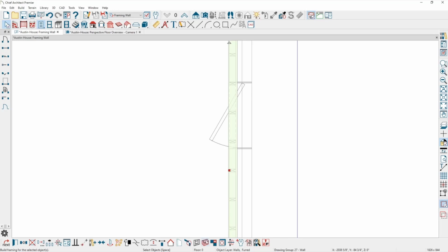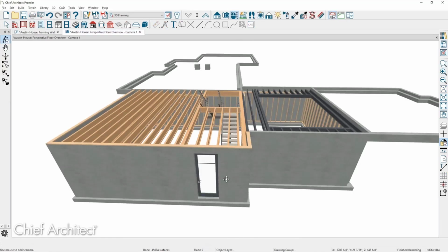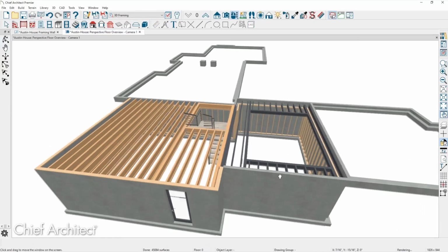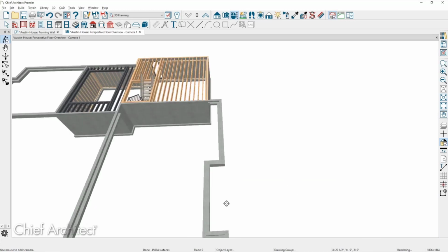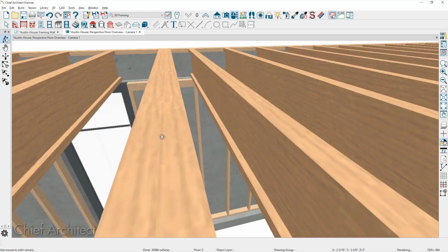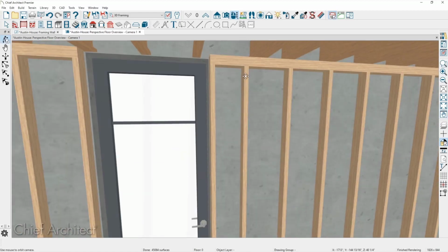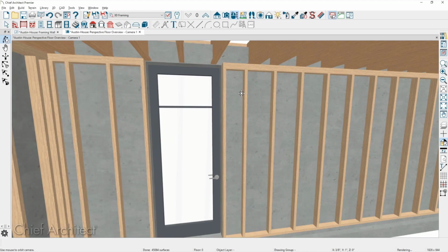There's an edit menu tool in my lower menu here to build the framing for that particular wall. Then you see the framing update, and let's go back in and peek around the other side. Of course, I put in a great big door that's going to stretch and have no header in there. So I may need to pull that down so we get a header in there.